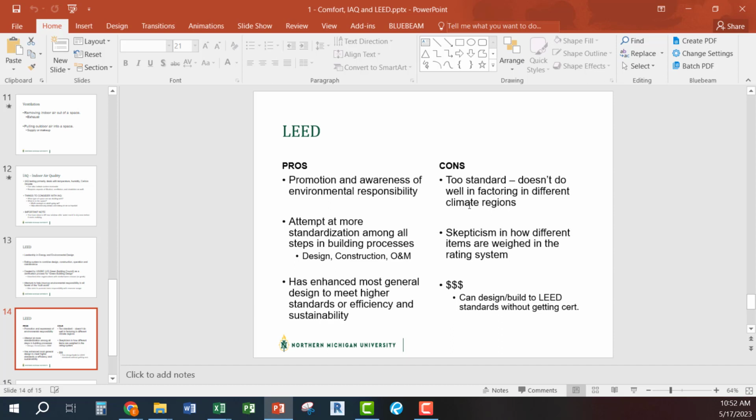For a long time, what I had a big problem with was that in Michigan we'd have to put white roofs on a building, where we actually have a lot more heating degree days than cooling degree days. In theory, because we are reflecting more of the sun's light away, we are making our mechanical equipment work harder all year round to heat and cool the space. It's really more about cooling the space at that point. But we couldn't get the LEED points without it, and then it makes it a lot harder to get the LEED points in mechanical components. So it's getting a lot better.